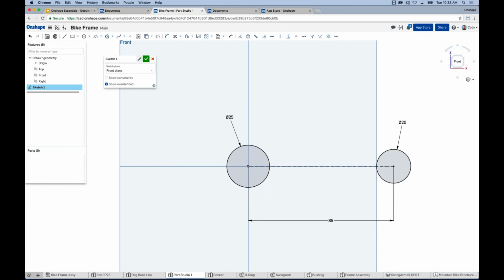Right, so let's do that. I'll select line, select one circle. Notice as I move my cursor over the circle, it highlights, indicating that I'm attaching my line to that circle. Left click. Again, I get that visual cue, that highlighting, indicating I'm constraining it. Left click. And now I have a line that's attached to the 2 circles.